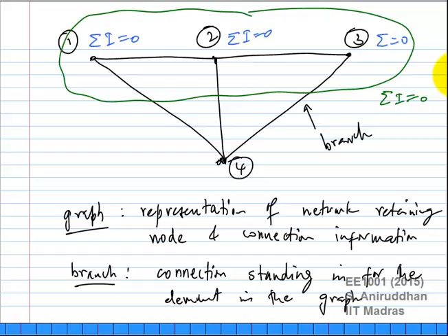And you can very clearly see, if you take a surface which includes all other nodes except for one, there is a relationship between the current leaving the nth node and what you write for the surface, and there is also a relationship between what you write for the surface and all the KCL equations you write inside. I hope this is intuitively clear to all of you, right? Because of this, you will always get only n minus 1 independent KCL equations.